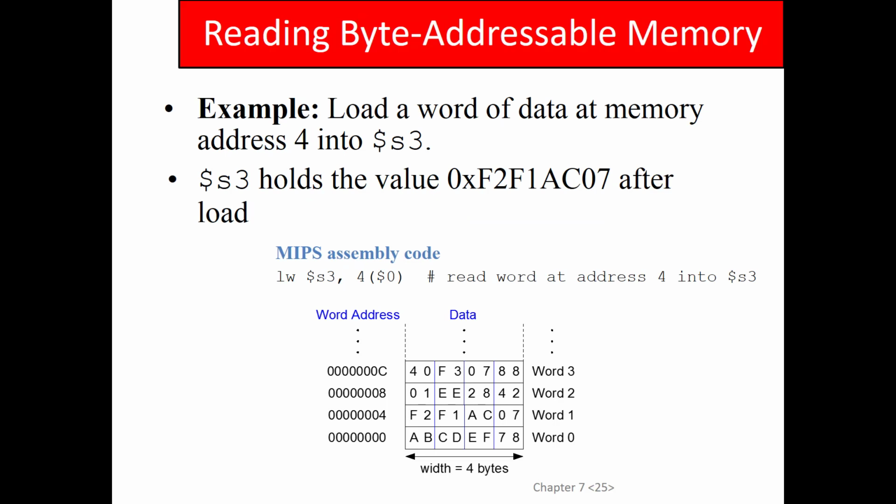Yeah, so this is a nice picture. This shows word 0, word 1, word 2, word 3, and then the addresses would be 0, 4, 8, and 12. And then you can see that you've got individual bytes in there, right? But this causes another problem, by the way. Your memory now becomes sort of a two-dimensional array, where one dimension is words and the other dimension is bytes. So if you've got memory organized like this, you give it a word address, and for every word address, there's potentially a byte address if you wanted to select one of the bytes out of there. You guys with me?